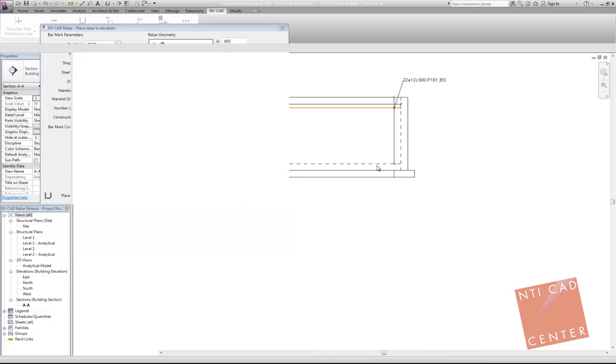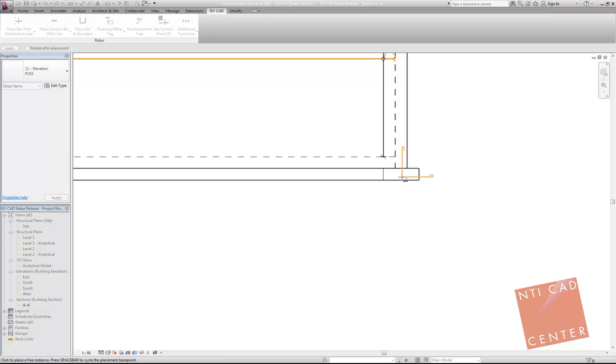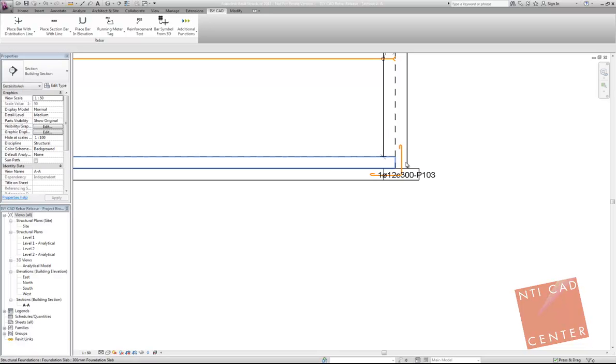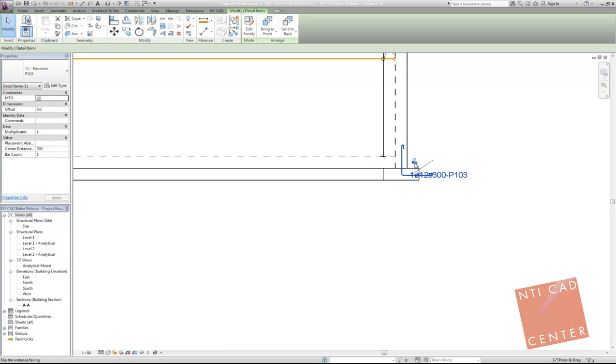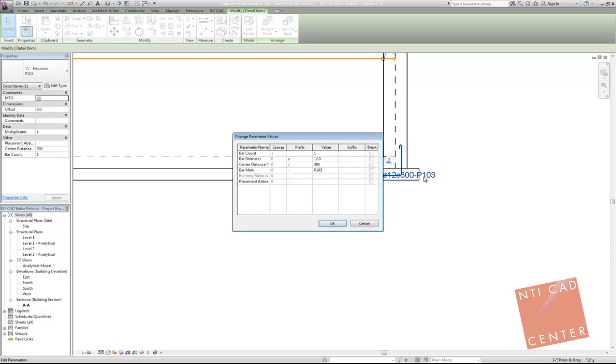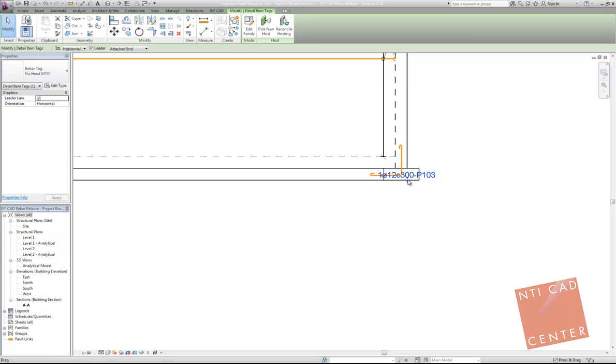Yep, place it there on the other side. And upon placing, I can click on the spacebar, which basically rotates the element all around. When I place it, I can still use these blue arrows to flip the rebar if I want to, or move it, modify its location, place, and so on.